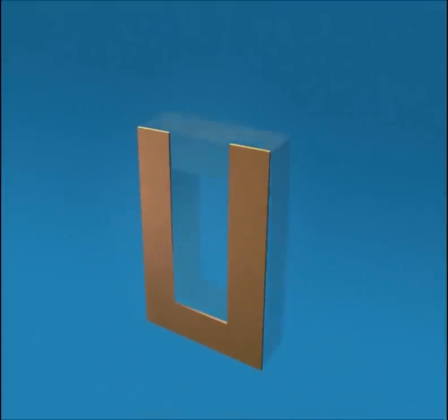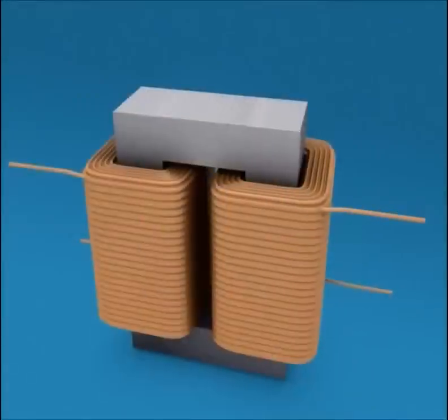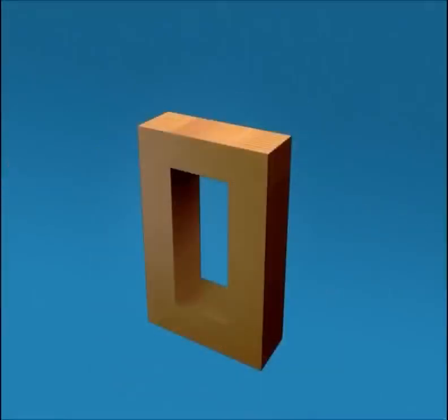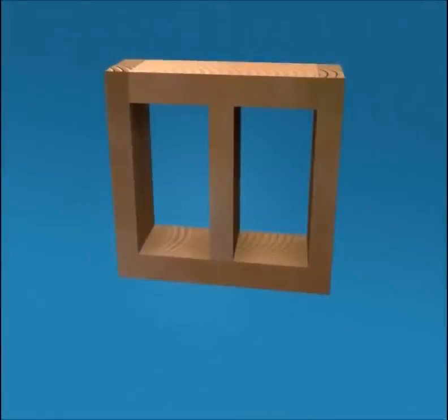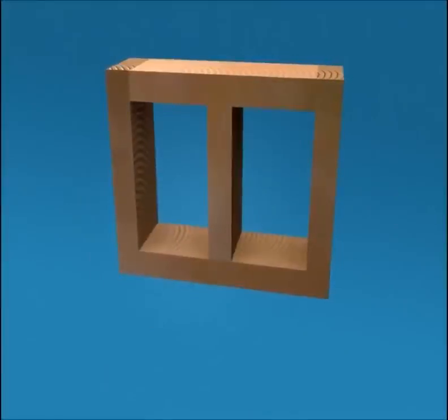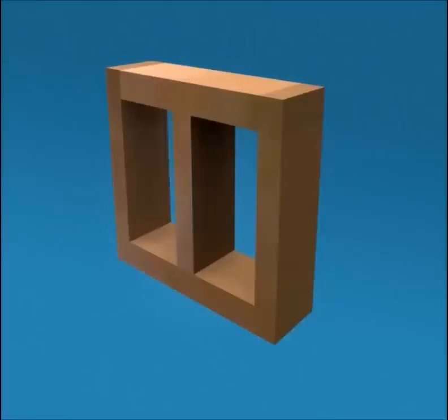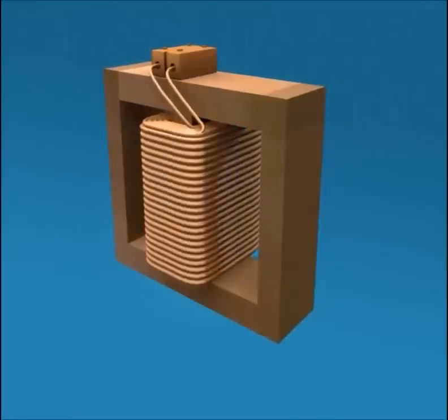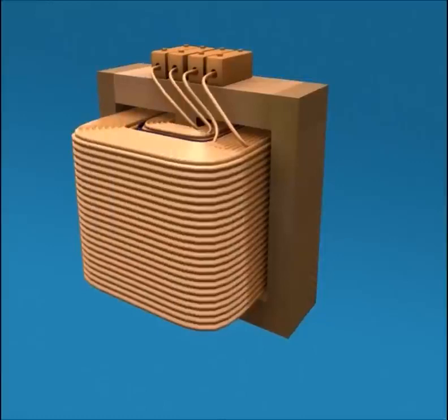The problem with the construction discussed so far is that the two windings are well separated from each other, and there is a considerable reduction of magnetic coupling and hence of the efficiency of the transformer. This disadvantage can be overcome by constructing the core like this, in which the two windings are brought close to each other, thereby improving magnetic coupling between them.